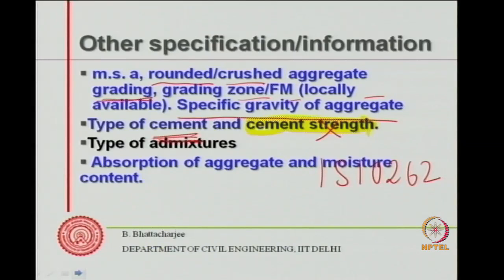Absorption of aggregate and the moisture content of the aggregate. This is important information. This we will have to know. We measured the moisture content at what is called saturated surface dry, SSD condition, which we have seen earlier. So we measured the moisture content required for attaining SSD condition from bone dry to SSD condition.